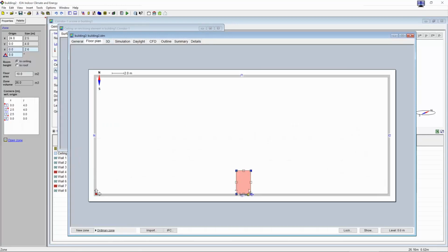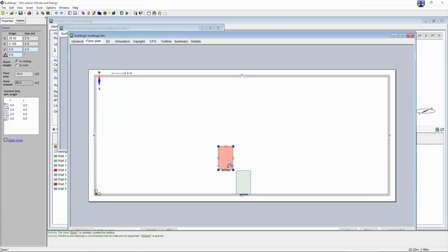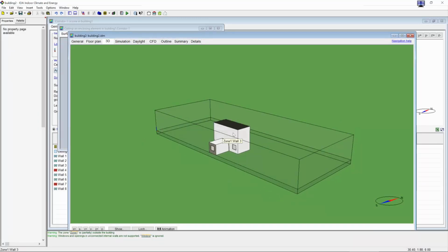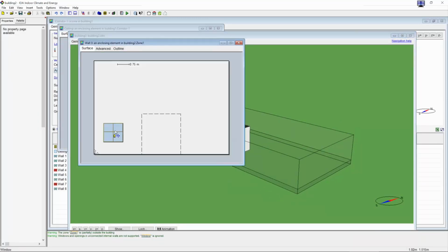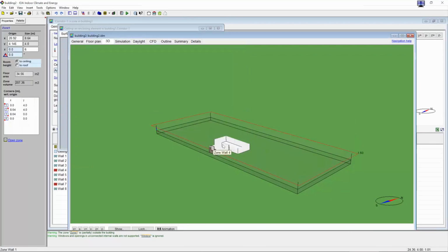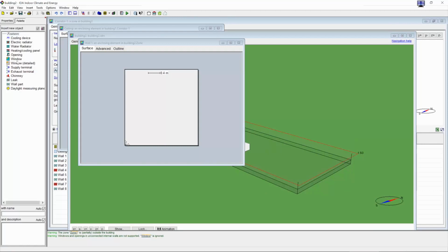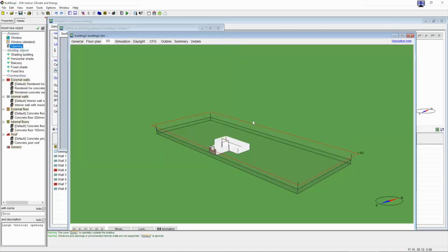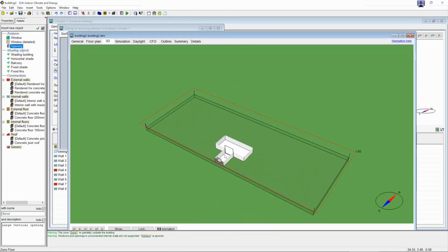If you, for instance, have a zone with a higher air space in the back, like this, and you want to have one zone here, or one room, with just one airspace, many users insert a big opening here, because they know that you can also select an opening without door, and you will get one airspace here.